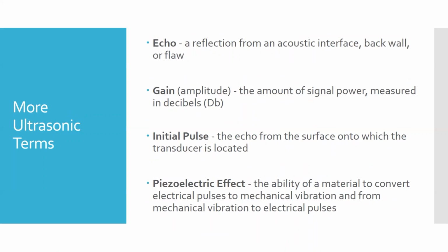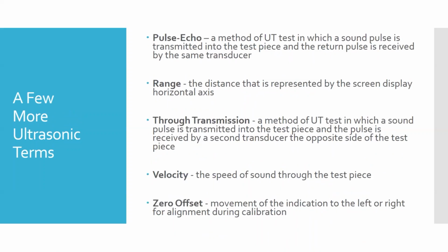So it essentially converts mechanical vibration and mechanical pulses to electrical pulses. It can convert electrical pulses to mechanical vibration, which produces ultrasound. You know, sound is just a mechanical vibration, a movement of particles either in the air or in a solid. So we use primarily piezoelectric crystal transducers in order to perform ultrasonic inspection.